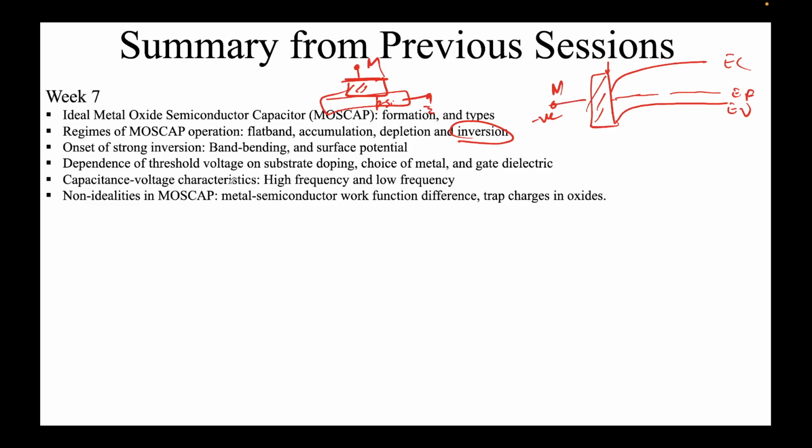And we saw the capacitance voltage characteristic also in both of high frequency and low frequency regime, if you recall, CV. So on the negative potential is the accumulation. So there it will be only equal to C ox. So this is your C oxide, epsilon ox by T ox. The oxide is here, right?